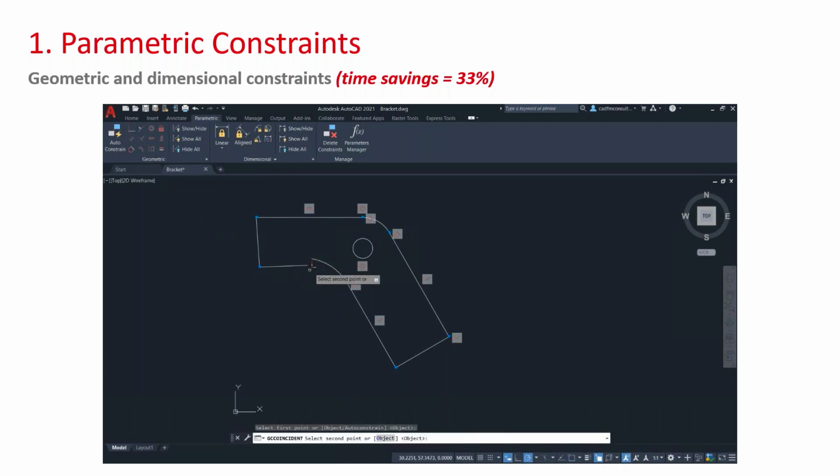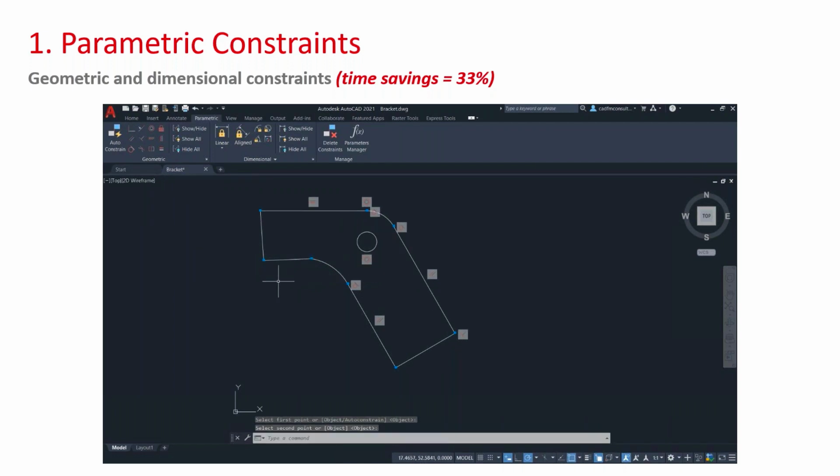And then I'll make sure that we've got some coincident points to join up that gap. So those points now are always coincident together. And then we'll start working on some of the line work there, making sure those lines are parallel to each other. And then we don't want a wonky corner there, top left, so we're going to make sure that that's perpendicular as well. So all of those constraints will hold that bracket together now. And that's our geometry in place.